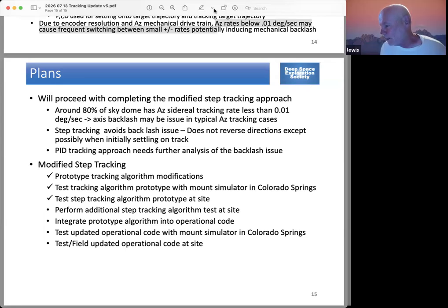In the system one, there's no compensation for that. The motor controllers themselves can handle that. For instance, the Copley controller controls the current going to the motor, and it's doing a control loop at, I think, 14 kilohertz.